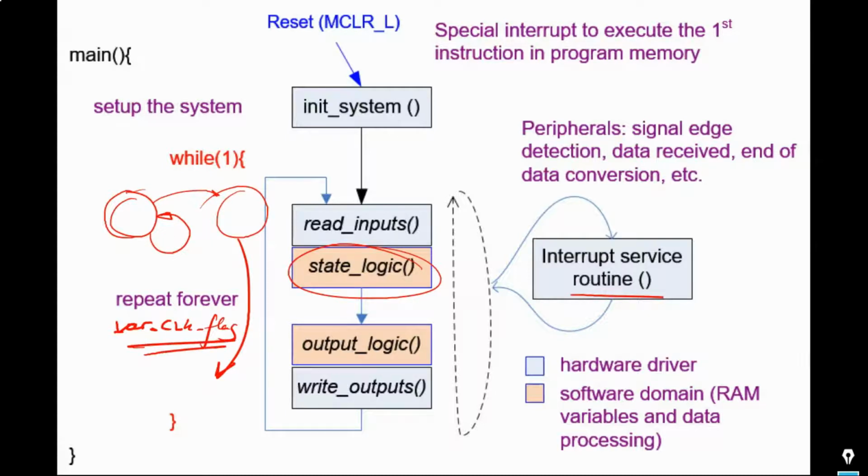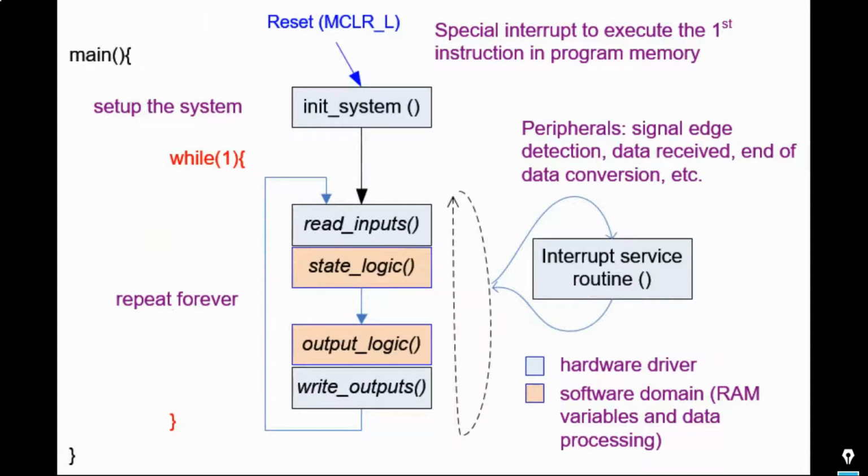For many applications you have an external clock or perhaps an internal clock from a peripheral timer that generates clock ticks, and you have to detect them so you can advance the machine from one state to the next. We can do that because after the system has been interrupted, you go back to the main program with this flag set.